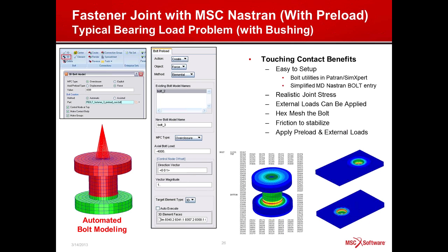So obviously here, it's easier if you have a clean interface, as shown here with the fastener that's in hex mesh. It's doable also with tet mesh, but it's a little bit harder to select, but still it's doable. And it's also doable using 1D beams. So if you have typical shell assembly models and you have a 1D beam fastener, you can have just an extra node in the middle and break it there using that utility and induce the preload to the structure.